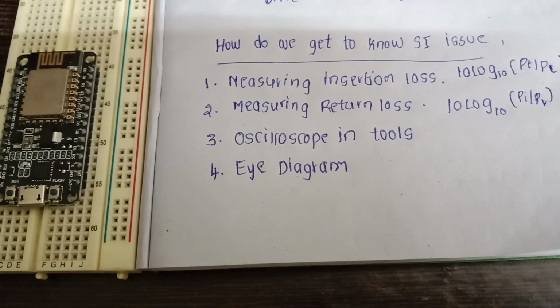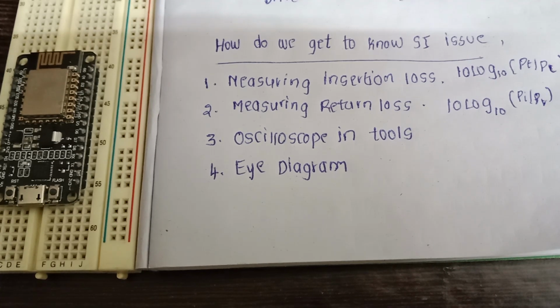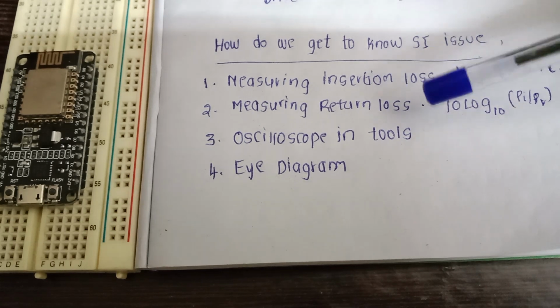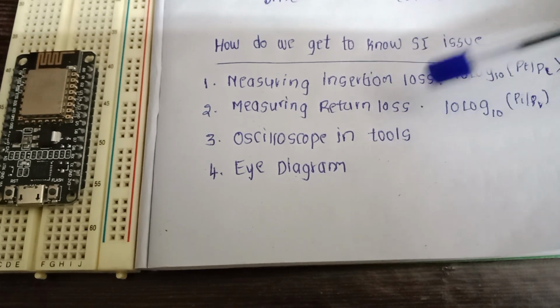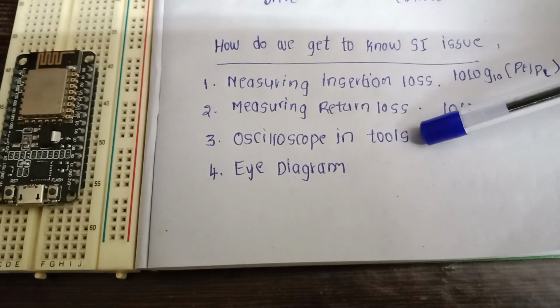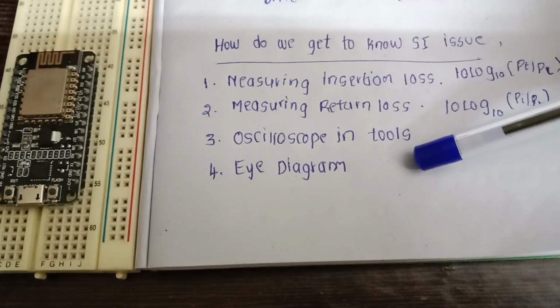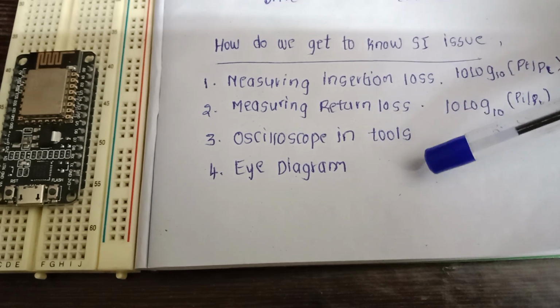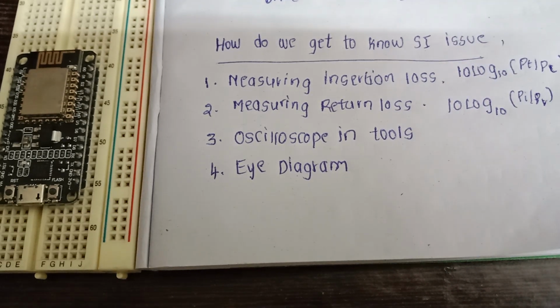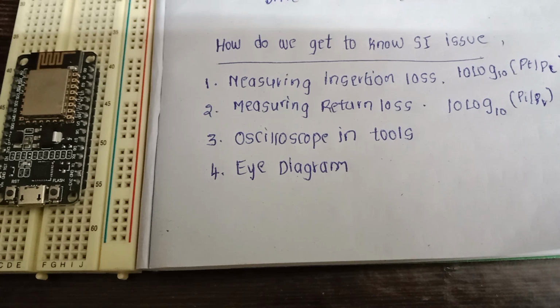So this helps us to know the performance of the channel, and if there is any intersymbol interference in the channel. The jitter which we see gives us an idea. Very useful tool. So if you see that in the oscilloscope your signal is good and there isn't an issue, people don't go to the eye diagram, because there it is already very clear and your signal doesn't have any anomalies, right?